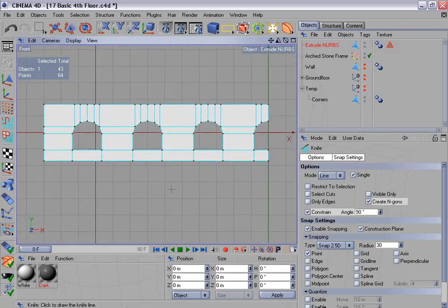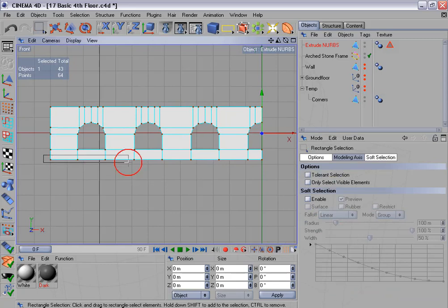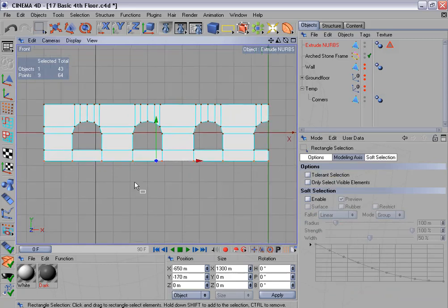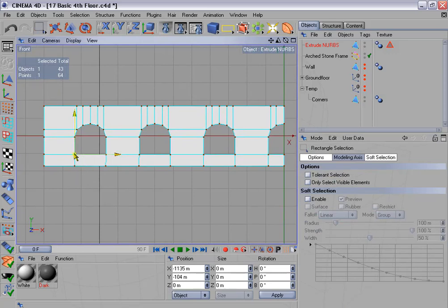Okay, and now we have to align and reposition some of these points, which is again the same thing that we did on the ground floor wall. Don't have to change anything for this bottom row, and on the second row from the bottom, just select one of these original window points as a reference, copy the Y position, and we only have one new point here, so we only have to paste the Y position here to align these points.